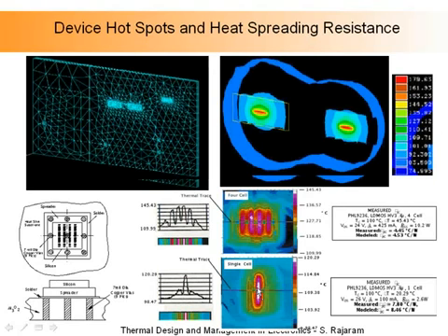But here's the interesting thing. Look at what is happening on the chart over here. This particular device has 4 devices here, and the thermal resistance of that is only 4.5. Whereas this particular one is a single device, its thermal resistance is actually 7.8 to 8.